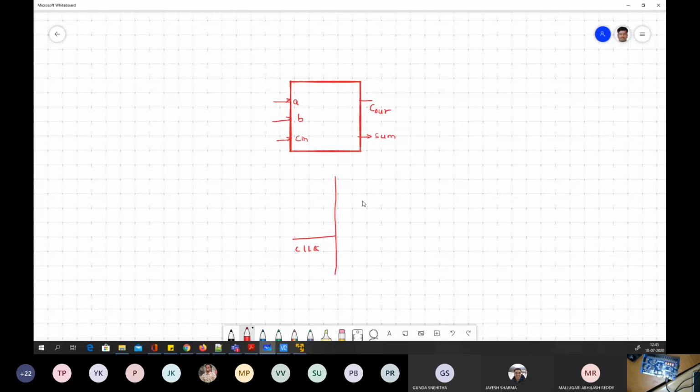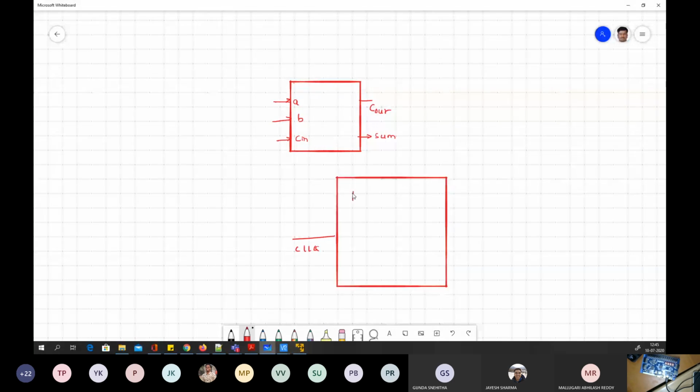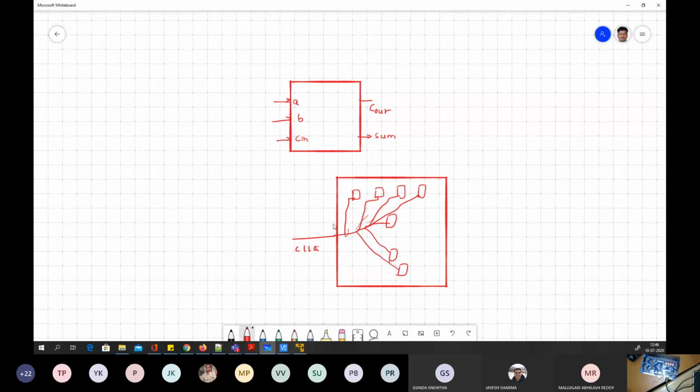If, for instance, let's say this is your complete IC, there might be a flip flop here, a flip flop here, a flip flop here. There are millions of flip flops in your design. And the same clock has to go here, and here. Sorry, bad drawing. The same clock has to go to all of these. You're trying to really distribute this clock to many flip flops.